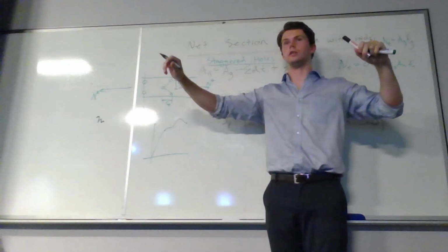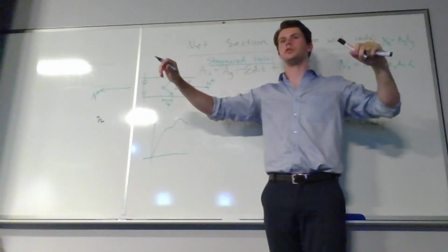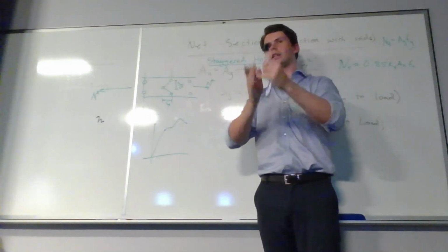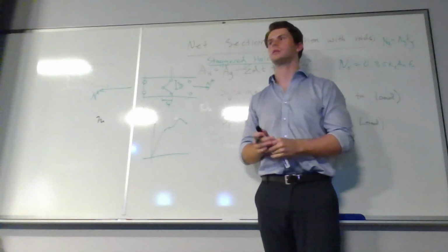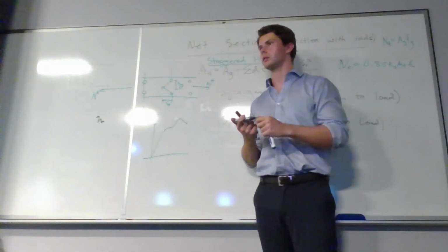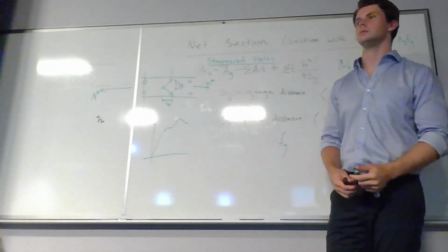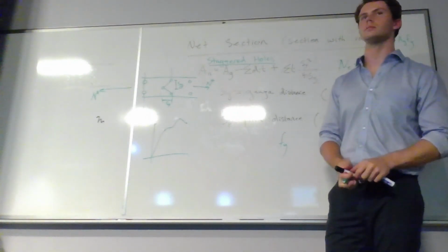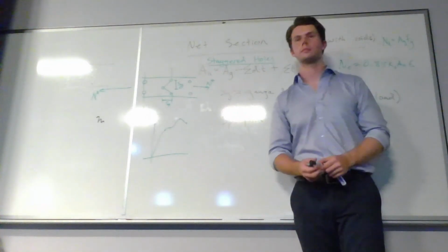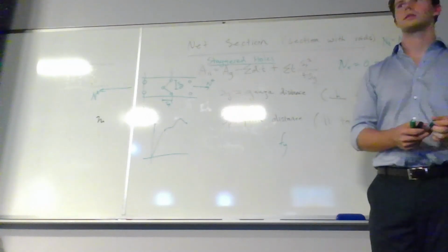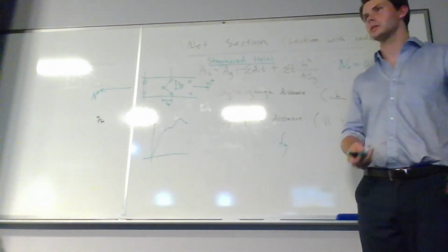Yeah. Just because you get all these dislocations of molecules and stuff like that. The stronger just meaning it'll take more load. Like once it's yielded, you can keep stretching it because it hasn't broken yet. It's not snapped yet, right? Sure. So you can keep increasing the load on it, and that's why it goes to the hump on the top, and then eventually it'll snap.